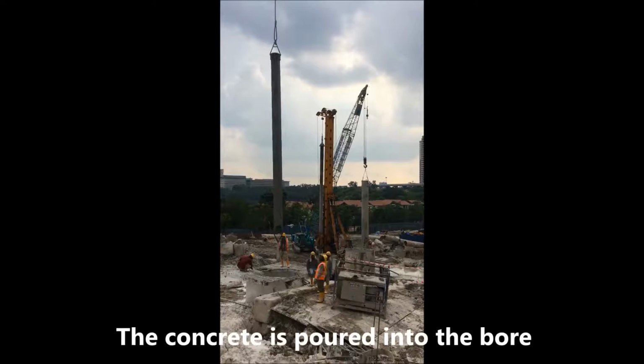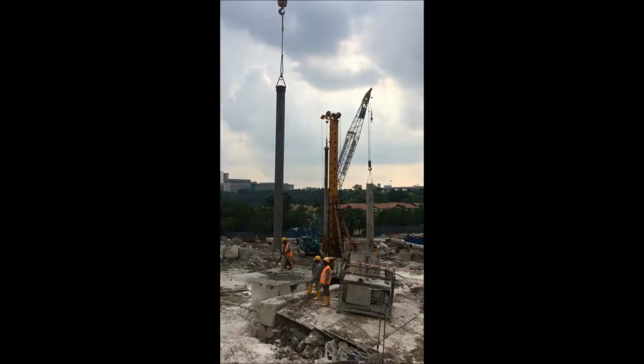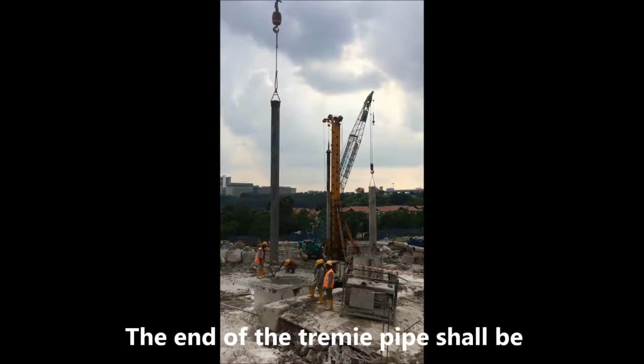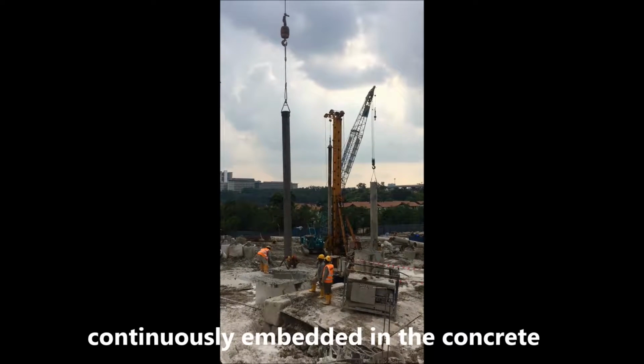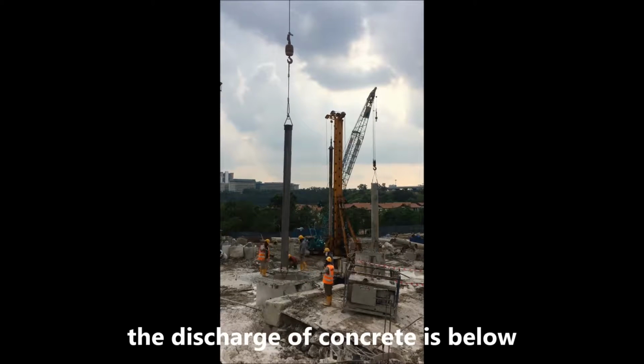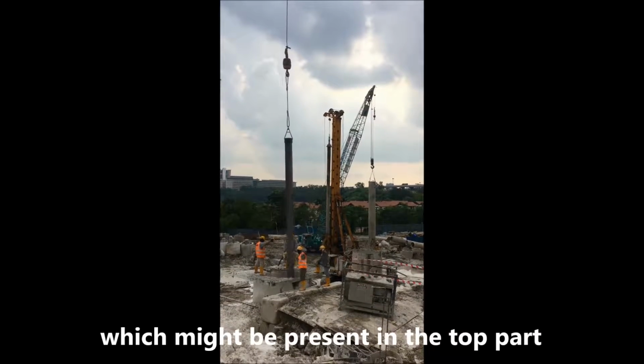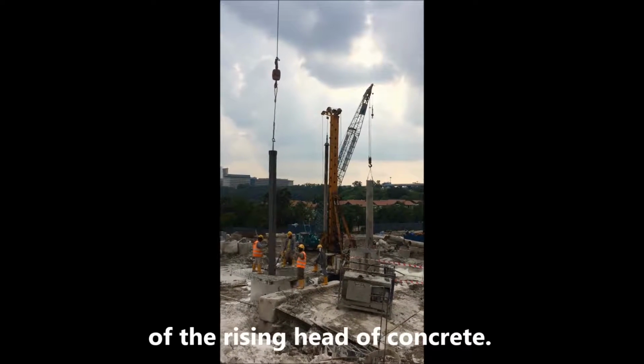The concrete is poured into the borehole through a tremie pipe. The end of the tremie pipe shall be continuously embedded in the concrete during this process to ensure that the discharge of the concrete is below the level of the impurities, which might be present in the top part of the rising head of concrete.